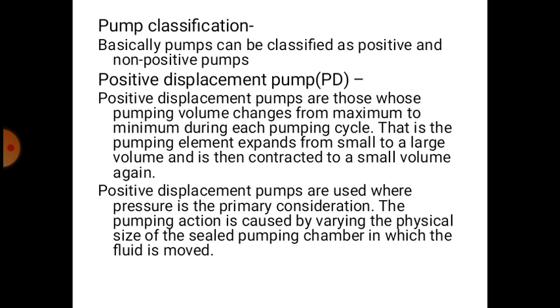Pump classification. Basically pumps can be classified as positive and non-positive pumps. Positive displacement pumps are those whose volume changes from maximum to minimum during each pumping cycle. That is, pumping element expands from a small to a large volume. Here the volume goes on increasing and suction is going to take place. That is, the pumping element expands from a small to a large volume and is then contracted to a small volume again.